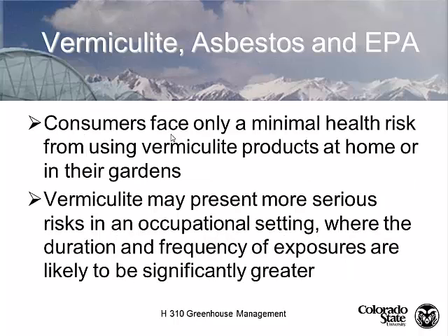So consumers are confused about this. EPA is saying that most of the likelihood of exposure to asbestos is minimal. If you're worried about it, wear a dust mask. The primary thing that we're recommending to people that handle vermiculite, if you're afraid of the asbestos dust, which it doesn't have because the only mine in the United States that has asbestos related to it is the one in Libby, Montana. All the ones out of the southeastern Appalachians are not contaminated with asbestos, is to just wet down the mix a little bit with water to knock the dust back.